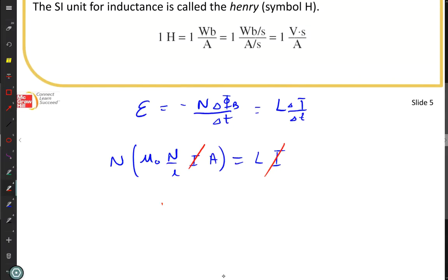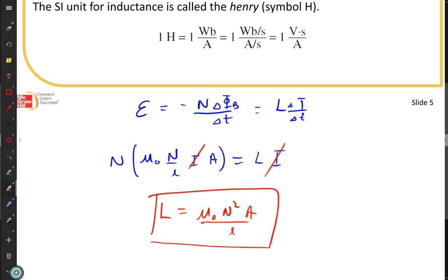And we have the inductance, the physical inductance, mu naught N squared times the area over the length. I don't think I made any mistakes. Well, actually, it looks different on the coming up pages, because instead of area, they put pi r squared. If it's a circular coil, the area is pi r squared. So I was looking, I'm like, that's not the way it. So that's the physical inductance.